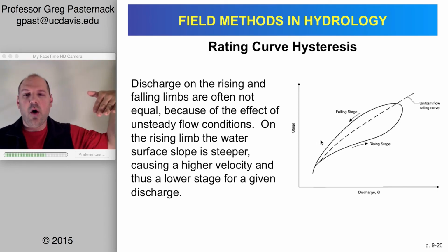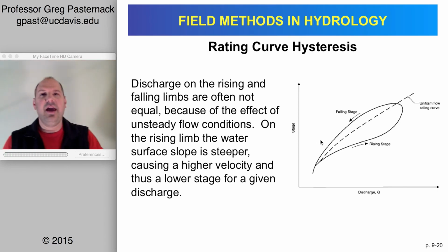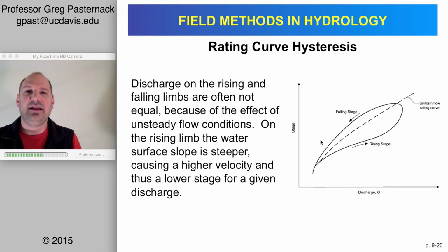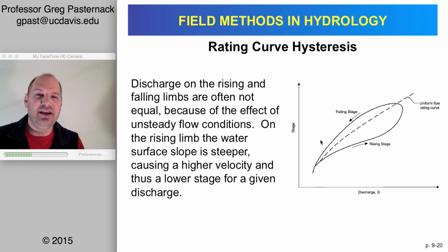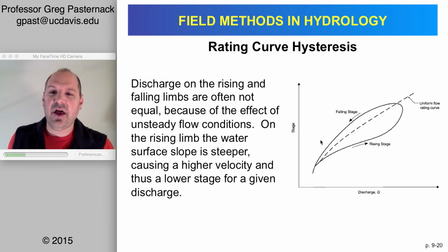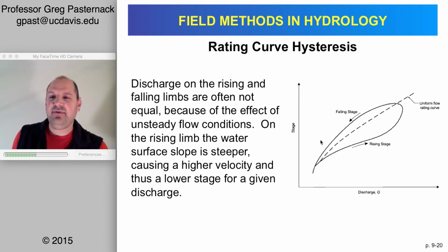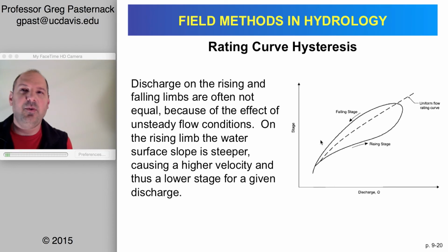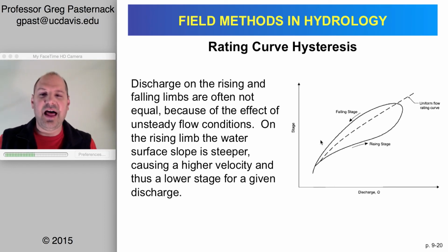First of all, the water surface might be quite sloped because you have a very quick response in terms of the driving discharge from the easily saturated areas near channel heads and in the channel. But then when you're drying out later, not only are you receiving flow and turning off flow from those areas, but you're now receiving flow from the groundwater system, which buffers the rate of decline of flow.